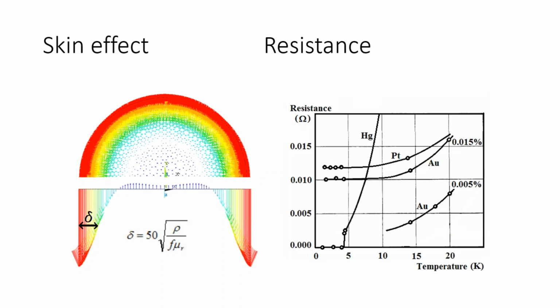Another phenomenon that makes this simulation a bit complicated is the fact that the material conductivity depends on the temperature. So basically, we're trying to compute a temperature rise in the workpiece, which is an electromagnetic system. But at the same time, properties of this electromagnetic system depend on the temperature. And this is why it is very important and very useful that EMS allows us to easily and seamlessly couple the electromagnetic and thermal solvers so that we can get a truly accurate and useful solution.